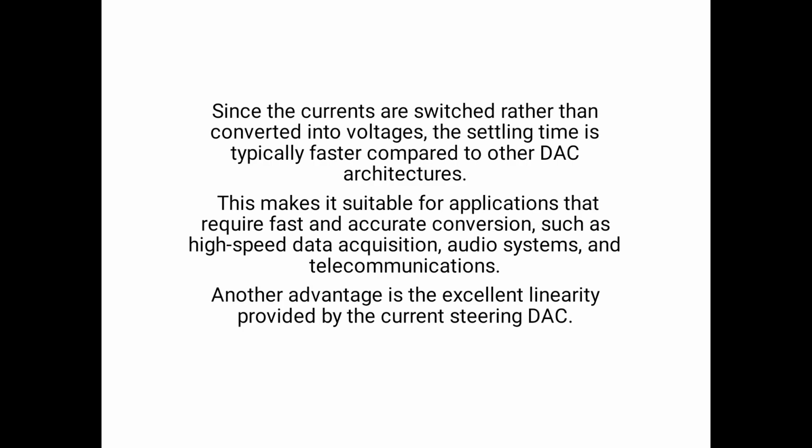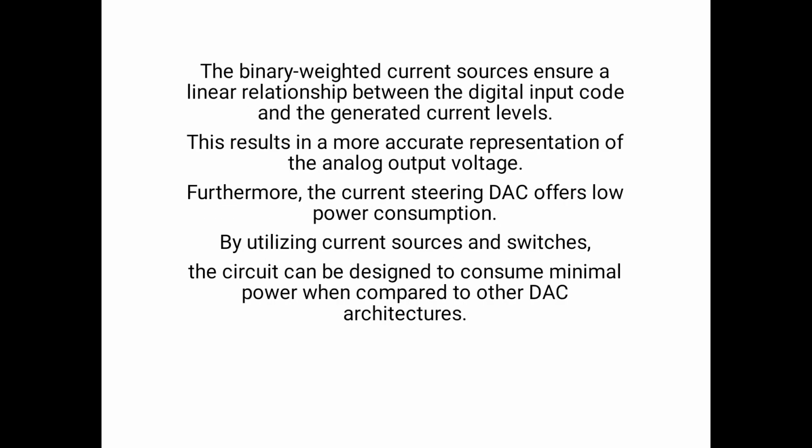Another advantage is the excellent linearity provided by the current steering digital to analog converter. The binary weighted current sources ensure a linear relationship between the digital input code and the generated current levels. This results in a more accurate representation of the analog output voltage.